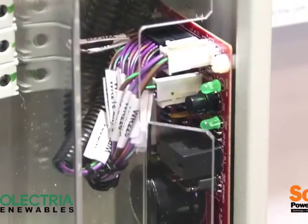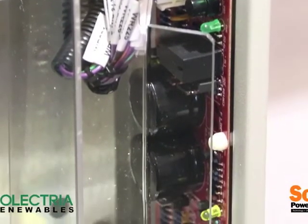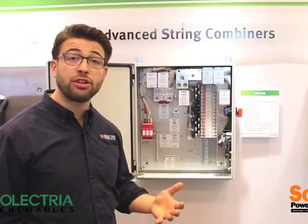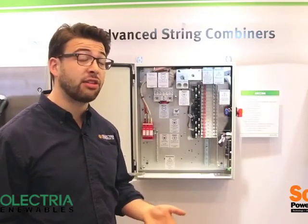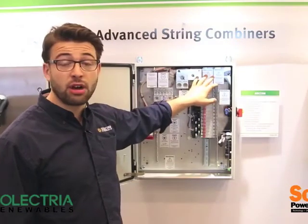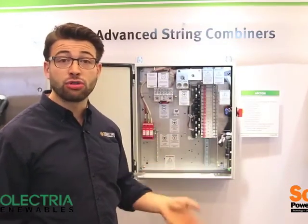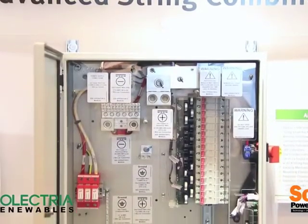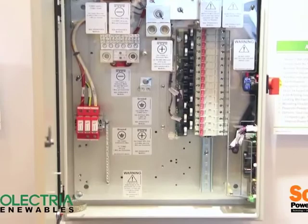The DC vacuum contactor also allows you to comply with rapid shutdown requirements. So you run power to the box, and when a first responder needs to come to the site and may need to activate the rapid shutdown system, they de-energize all the boxes, all the DC vacuum contactors open up, and then all of the controlled conductors on the roof are then de-energized so that the first responders feel safe venting the roof and cutting through DC conduit.